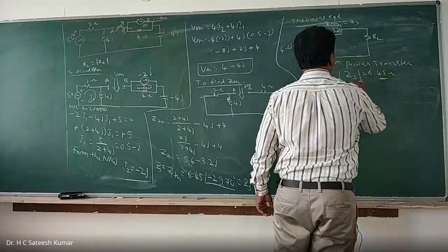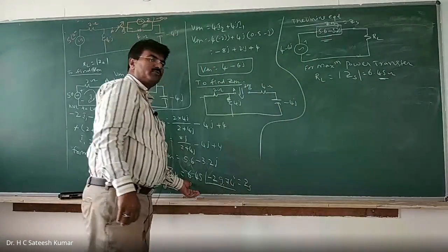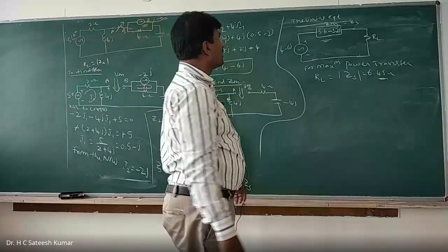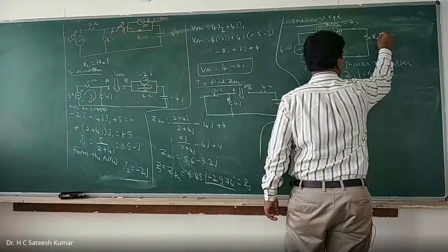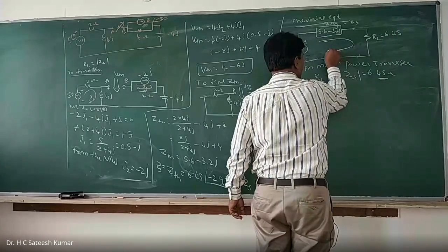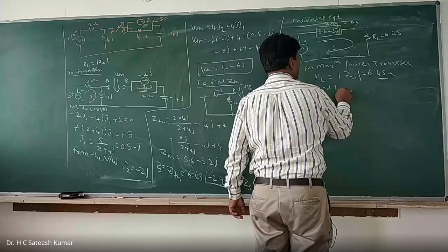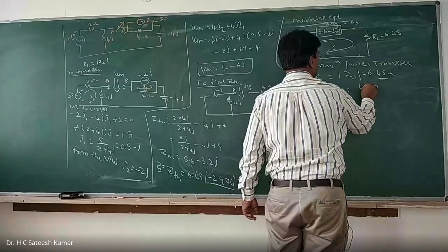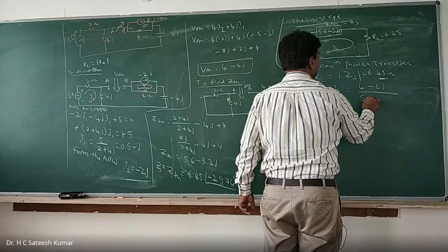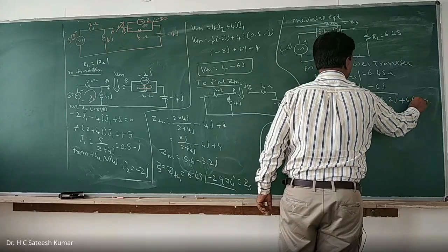That is the magnitude of the ZS, because ZS is this one. When you convert into polar, we get the magnitude with a certain angle. That is the reason why I said convert it into polar. Now, this RL is equal to 6.45. You should be very much careful. Now, you find out IL. To find IL, it is equal to what? 4 minus 6j complex divided by 5.6 minus 3.2j plus 6.45.